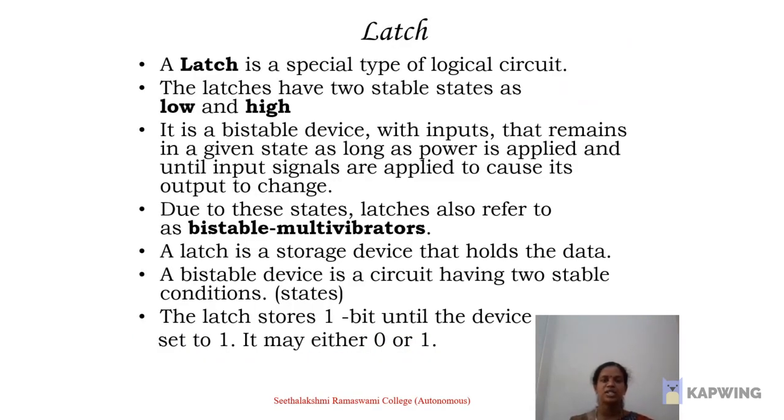Latch. A latch is a special type of logic circuit. The latches have two stable states as low state and high state. It is a bistable device with inputs that remains in a given state as long as the power is applied and until input signals are applied to cause its output to change. Due to these states, latches are also referred to as bistable multivibrators.